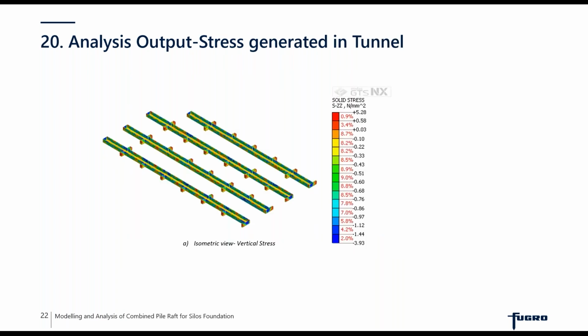One of the most critical aspects was how the tunnel is going to behave under such huge loading, whether it was designed to take the vertical stress coming from the silo loadings. We checked and found that the stresses generated were well within the acceptable limit of the grade of concrete considered for the tunnel.